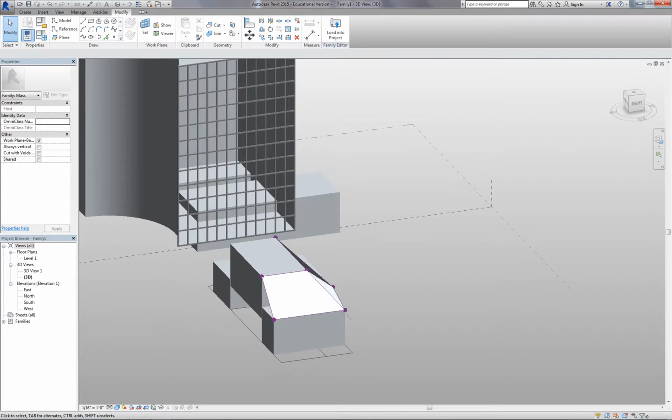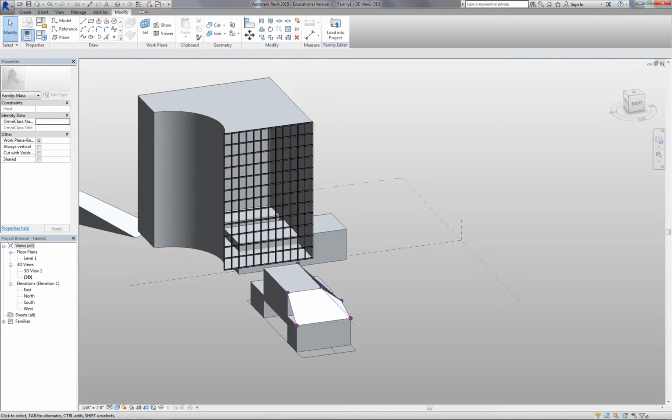You do curtain wall that way? This is the way I do curtain walls, yeah. Not the curtain wall tool. No. You want to jump out the window with that tool? No kidding. Make your own. Yeah, I do all the curtain wall stuff through here, and you can customize all the panels as much. This is really the way you're supposed to be doing it. At least that's the way I do it.